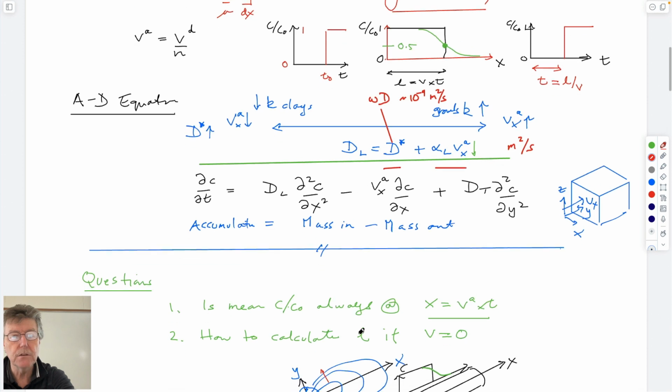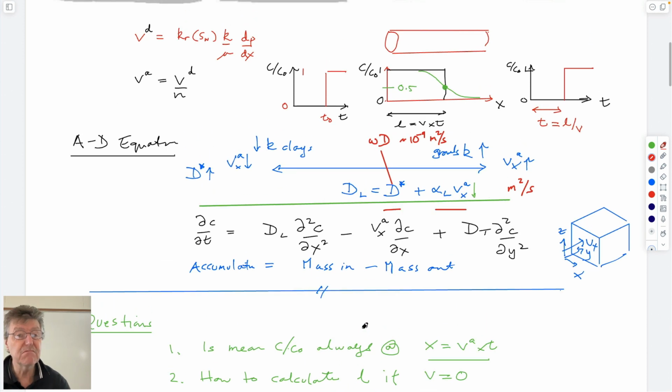So that's the equation that we're working with. We don't care all that much about solving the PDE from first principles, but we do care about knowing what it means, and we talked about both a step input in concentration and a spiked input in concentration. What those look like as they work through a core is that this pulse travels down by plug flow. If dispersion is 0, this is a sharp front, and it arrives down in the residence time distribution again as a sharp arrival.